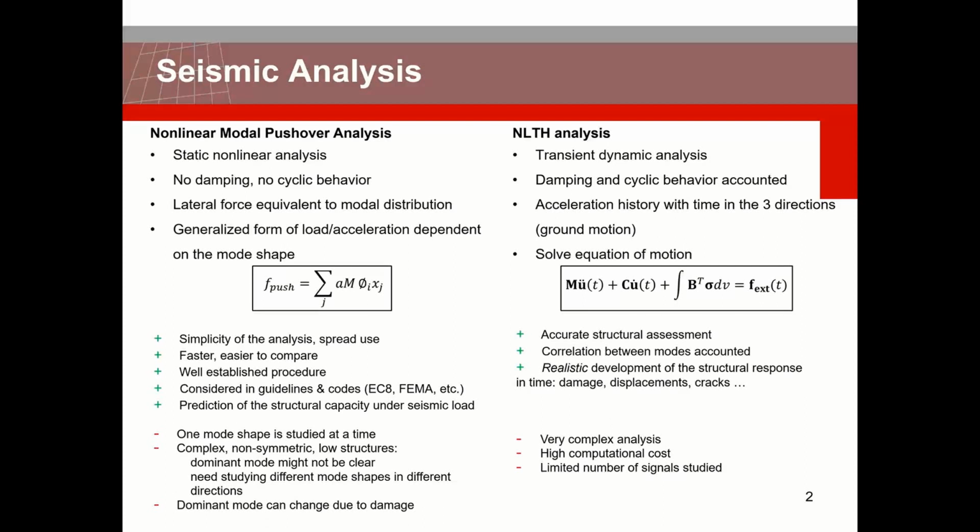And these analyses are quite simple and fast, and that's why pushover analysis is a well-established procedure and is considered in guidelines and codes to predict the structural capacity under seismic loading. Some drawbacks of this procedure are that only one mode shape can be studied at a time. So for complex and non-symmetric structures, the dominant mode might not be clear, and you might need to study different mode shapes in different directions.